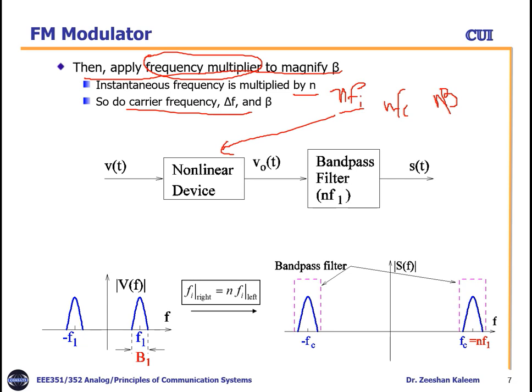For example, our target is twice the instantaneous frequency. So we need to filter the others. For example, this is our FM signal which we need to transmit. Right, this is the narrow band. When we pass it through the non-linear device, it will multiply by NFI, so there will be a number of terms, right? There will be a number of terms.